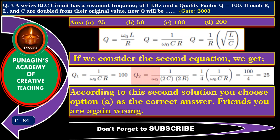Q2 is equal to 1 divided by omega naught into 2C into 2R, and we get Q2 is equal to 1 divided by 4 into bracket 1 divided by omega naught CR, and by solving we get Q2 is equal to 25. According to this solution, if you choose the option A as the correct answer, friends, you are again wrong. I will tell you why.